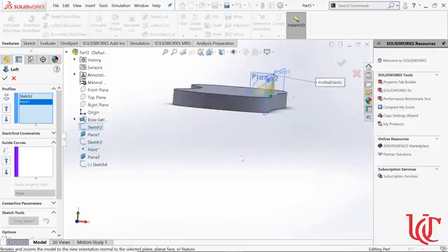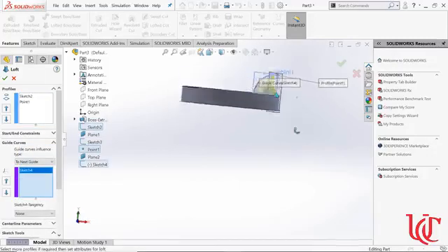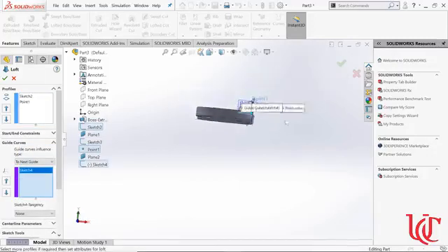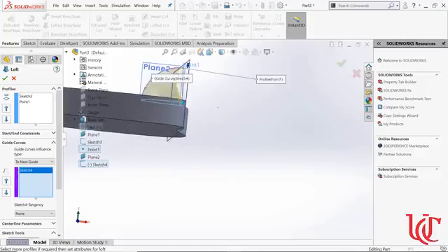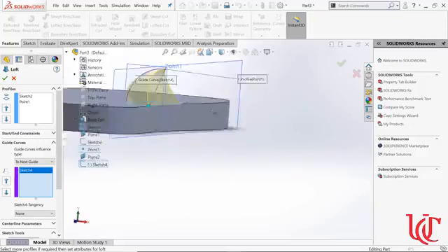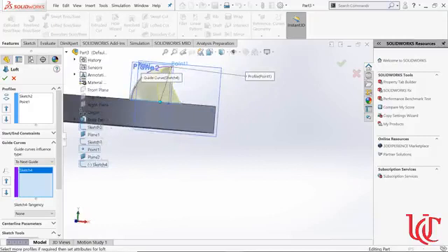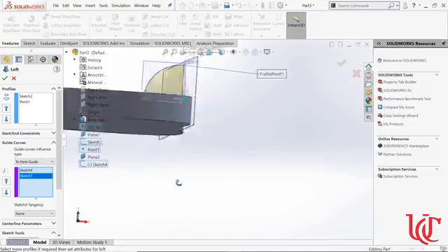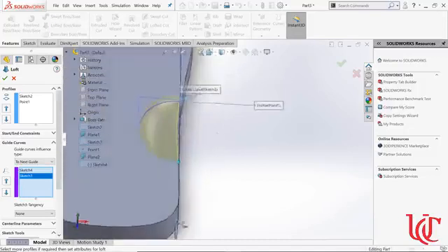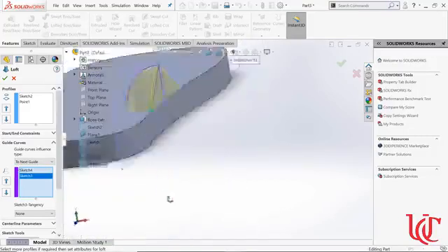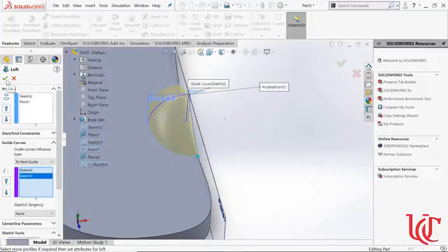Again, do you see how its default shape goes in a straight line from there? And if that's not the shape I want, I want it to follow this curve. So to make it follow this curve, I go to Guide Curves and select that curve there. Now, it's guessing that it wants to curve in on this side here as well, which is annoying. See how it curved in that preview? I can specify multiple guide curves. So if I select that sketch that was that vertical line, now it goes based on both of them. Now I've got a vertical line up from my center point and there. And that's my weird curvy shape using guide curves.